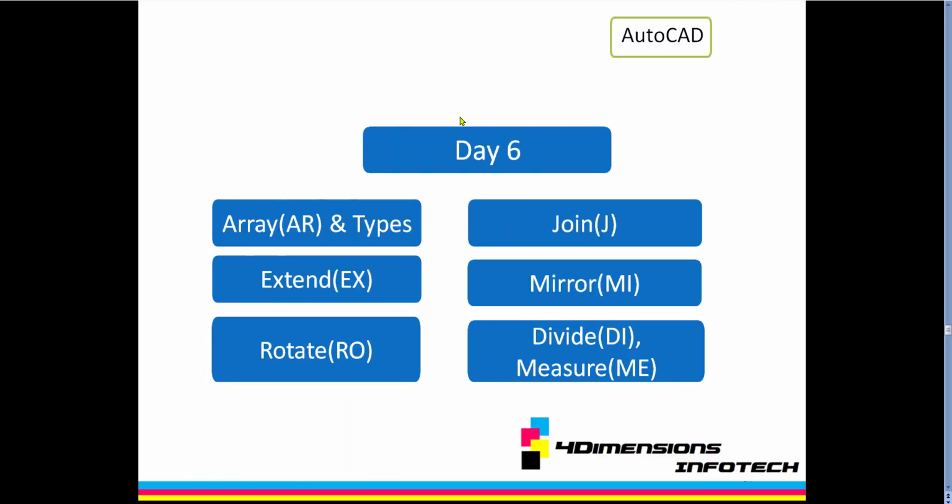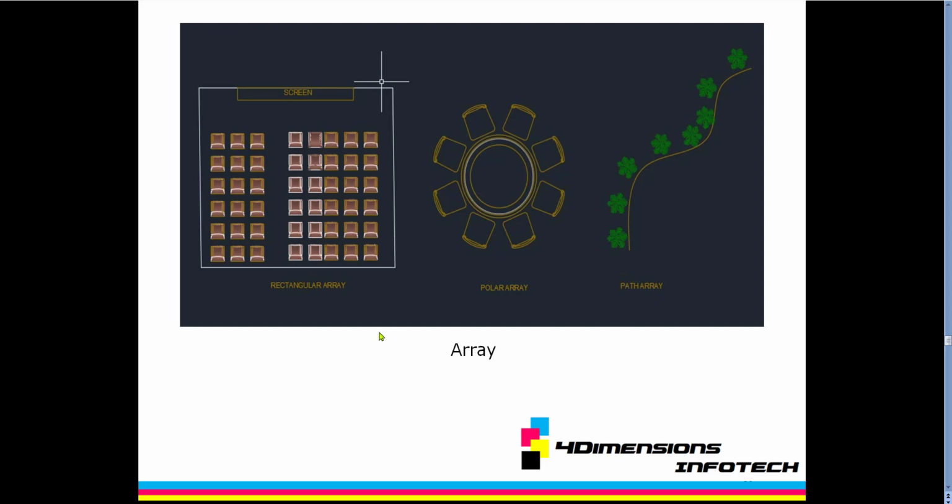Hello, in day 6 we are going to learn the commands like array, join, extend, mirror, rotate, divide and measure. In array we have three types, that is rectangular array, polar array and path array.